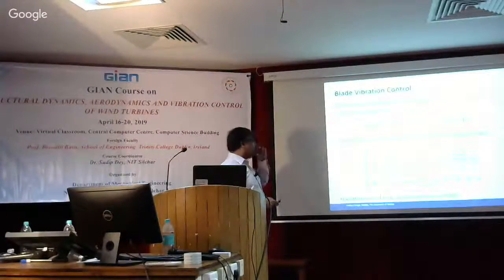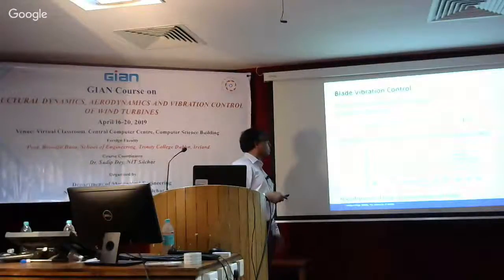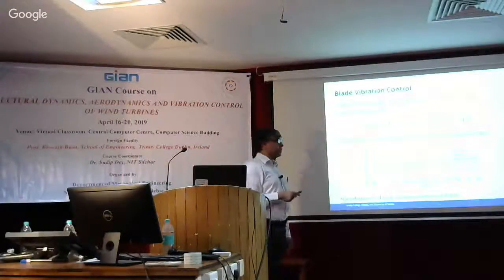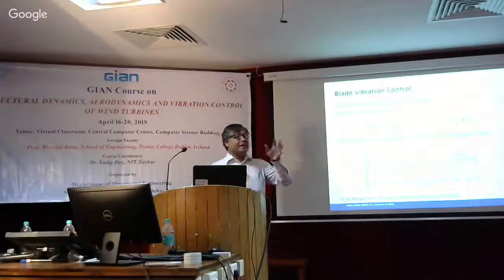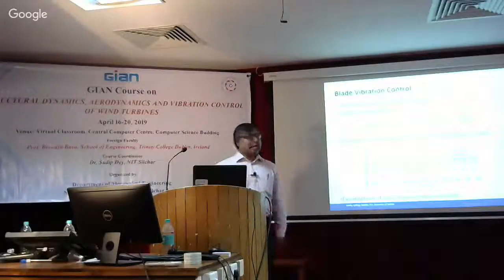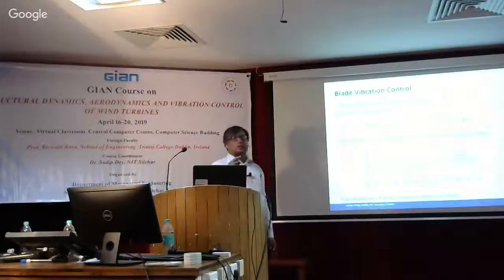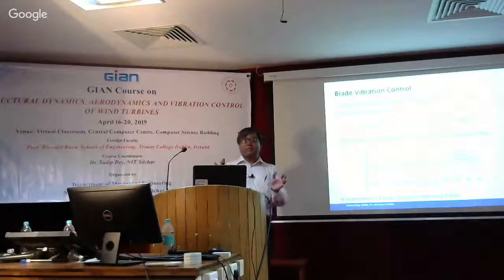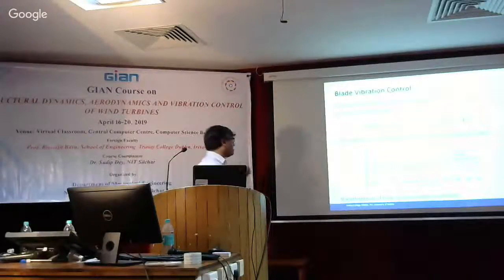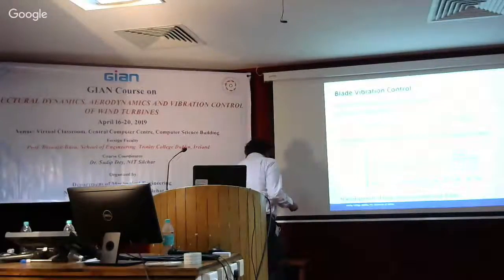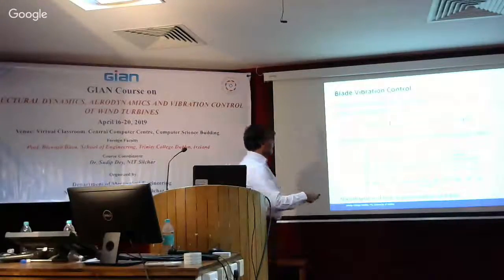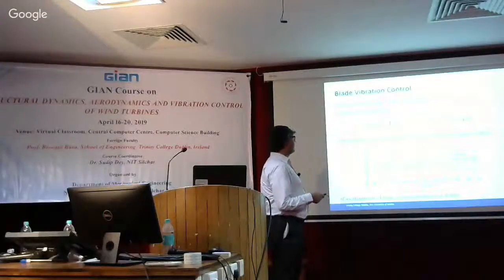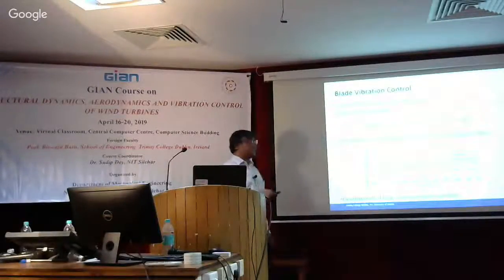So we can also use some tuned mass controllers, but we can't use TMDs because TMDs become unstable. If you just take a normal tuned mass damper and put it inside the blade, that doesn't actually work. And that doesn't work because there's a loss of stiffness, effectively due to the tuning effect, and that destabilizes the whole system. So we can use an active tuned mass damper. So that has again the effect of controlling the vibration.